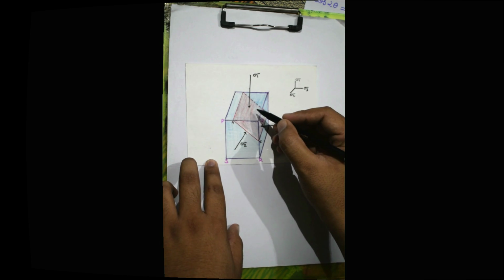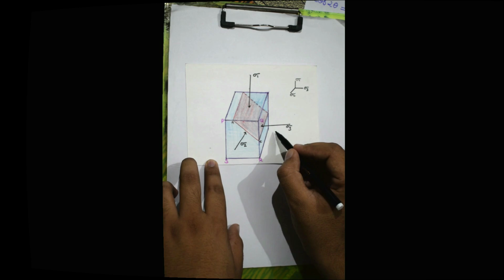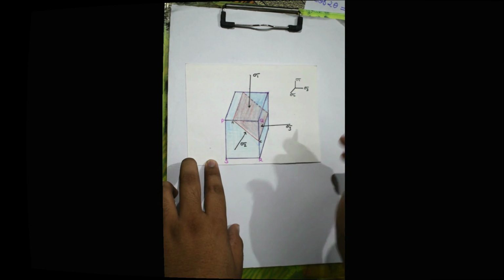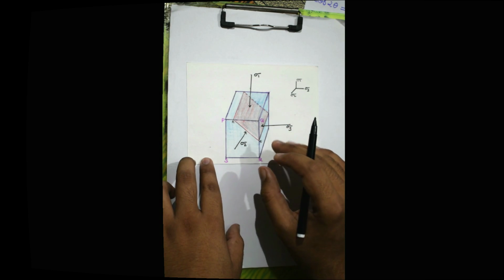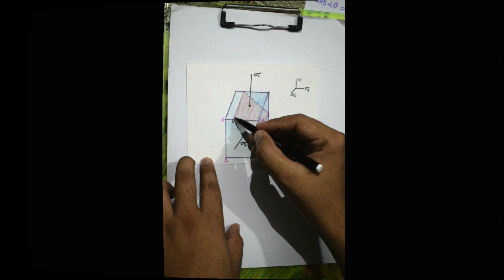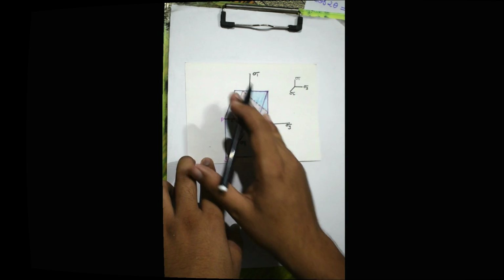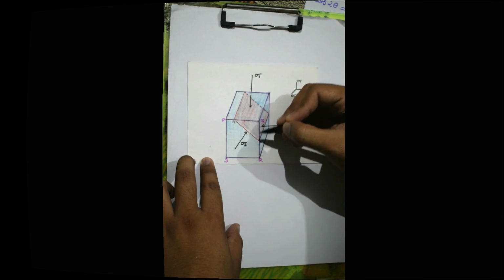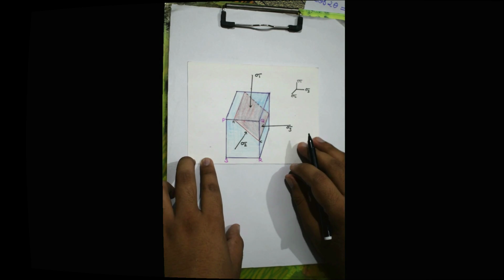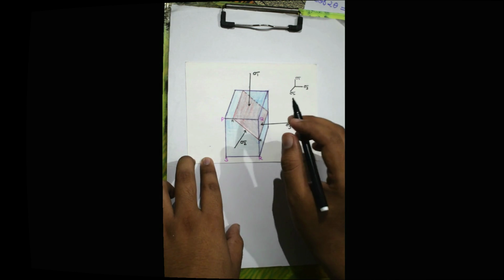This is the maximum principal stress axis, sigma 1. This is the intermediate principal stress axis, that is sigma 2, and this is the minimum principal stress axis, that is sigma 3. And because of this stress in this block of rock, there is a fracture plane or the fault plane that you can see here as a red plane passing through this block, and this is the trace AC of this plane. Suppose the area of this fracture plane or the fault plane is 1 unit.